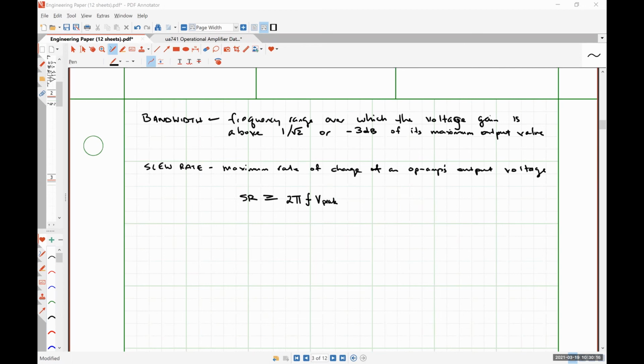What is the ideal input impedance? Can you justify that answer? Okay, fair enough. So our input signal, if this is an ideal op-amp, sees an open circuit. So that's why it has an infinite input resistance. All right. Output resistance, what should it be ideally?